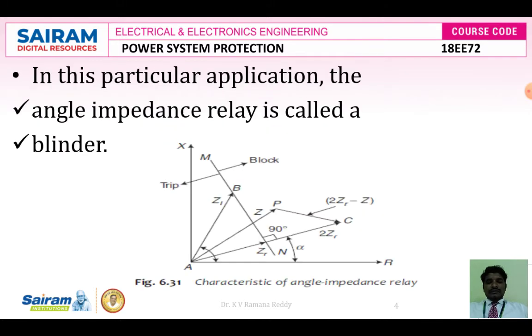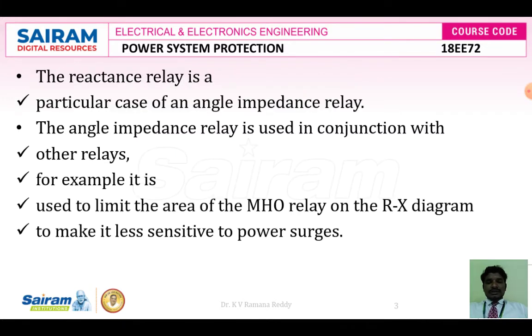So look at the figure. In this figure I am going to show the characteristics of an angle impedance relay, where the characteristics are inclined to the transmission line. As we already discussed the reactance relay, the reactance relay is a particular case of an angle impedance relay.